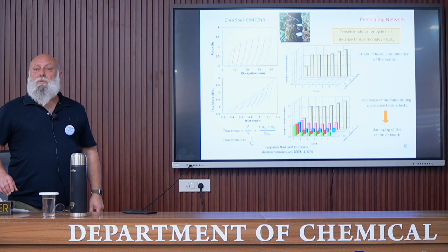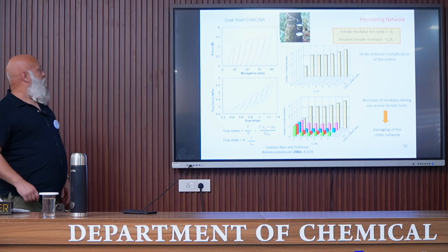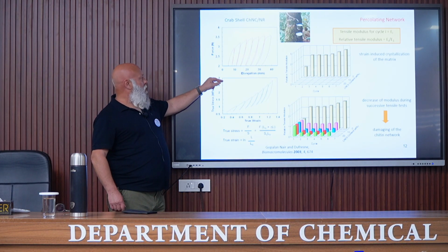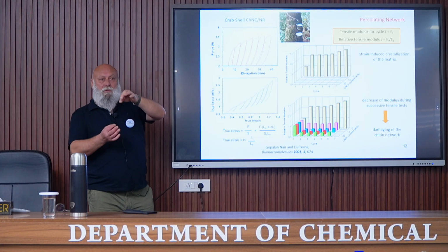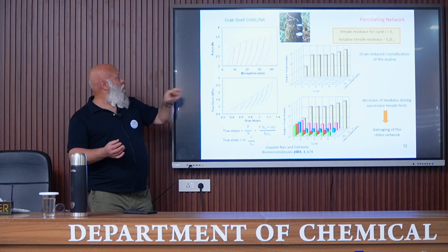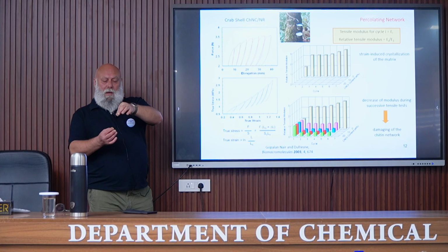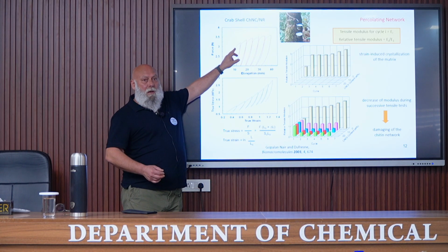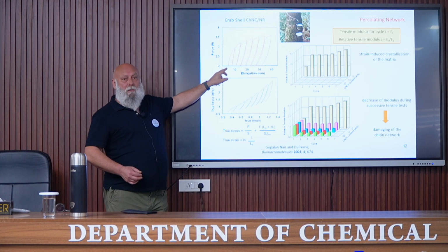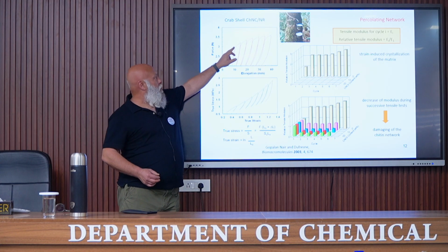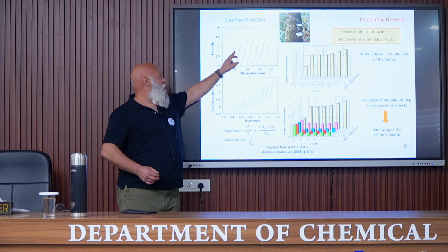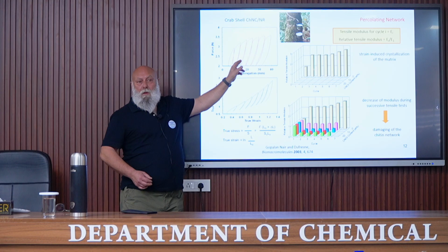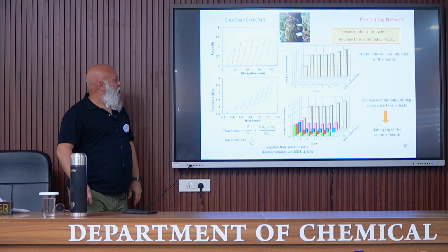He performed successive tensile tests, meaning that you can see here, force versus elongation. The material is first stretched up to a force of 2 Newton, and then it is stretched up to a given elongation, and then this force is released. And then it is stretched again up to a higher elongation, and the force is released again, and so on. We can describe several cycles.